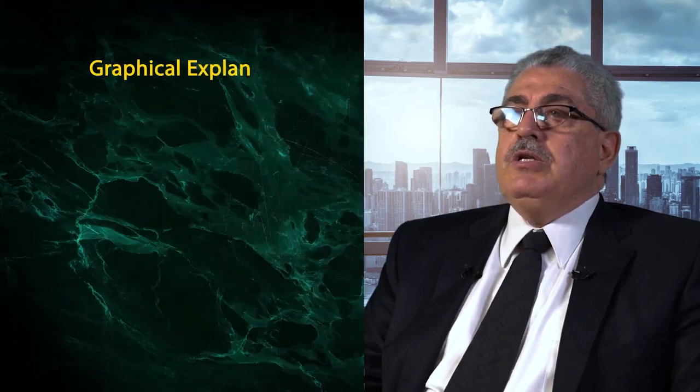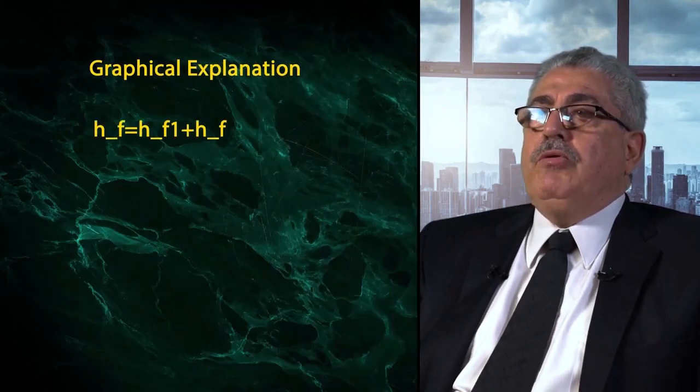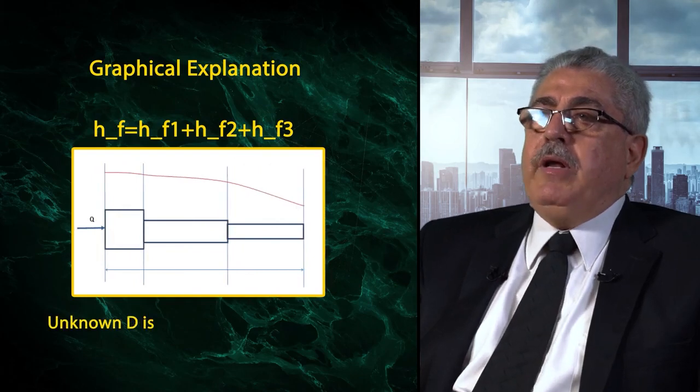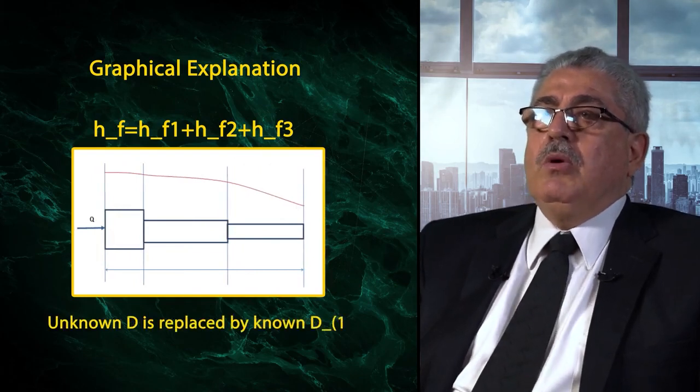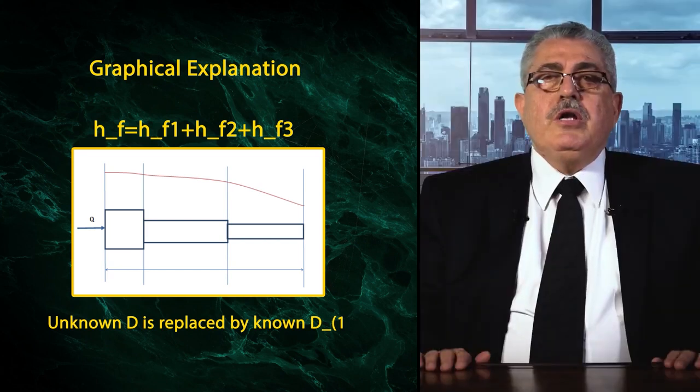This slide shows how we write the head loss equations in terms of the linear pipe segments lengths. This slide shows the total energy line for the pipe with 3 segment lengths after replacing the diameter D with the candidate diameter length Li, where i changes from 1 to 3. Linear programming. The spreadsheet now contains more design variables as mentioned before.